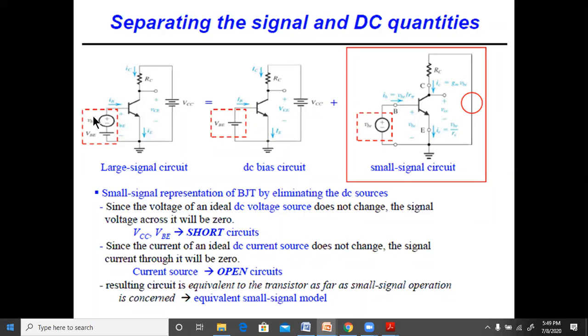Now, if you remove the AC signal, then only the biasing will be there. When we talk about the biasing, this AC signal is not there, and you are left with VBE only DC, and it becomes again the biasing values IB, IC, VC. All these are capitals. For instantaneous or total values, the suffixes will be capital but the letter will be small.